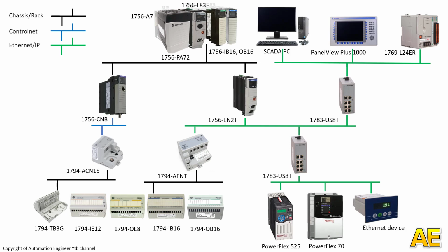Okay, that's the full connection of Rockwell Automation. Now I will share about the software to build this network. Firstly, for IP configuration, we use BOOTP DHCP. For the network configuration and browsing the device modules, we use RSLinx. For programming the PLC, we use Studio 5000 Logix Designer, or the old version is RSLogix 5000.